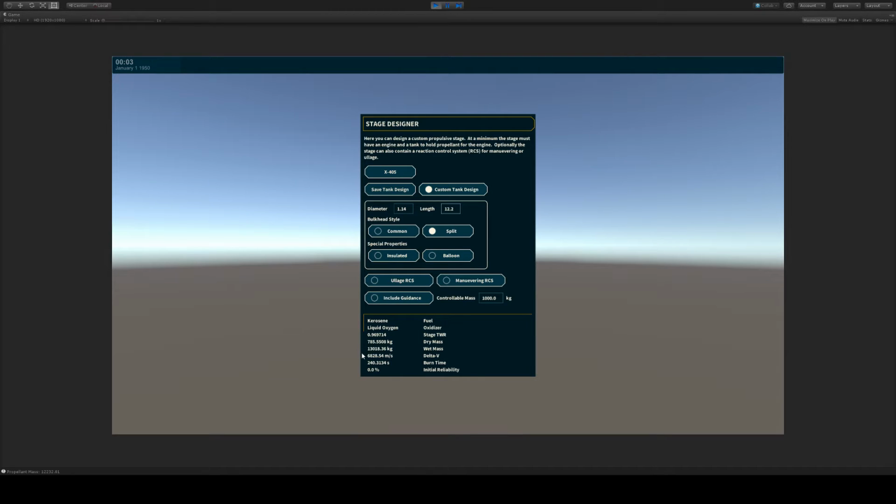Part of this is due to real life hardware not exactly meeting or fitting into calculations. Part of this also is the Vanguard first stage was 12.2 meters in height, but that also included the engine. And what we're computing here actually is just the tank by itself. So a 12.2 meter long tank is actually going to give us a lot more volume for propellant than Vanguard first stage. If I reduce to something around 8 meters long, the values would be a bit closer to Vanguard's first stage. And we can also make this insulated if we want to.